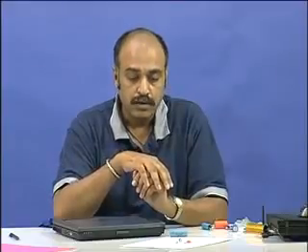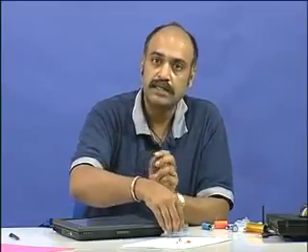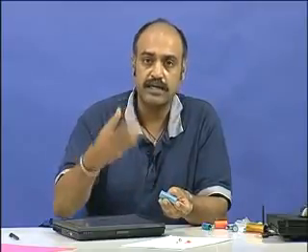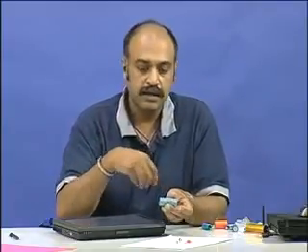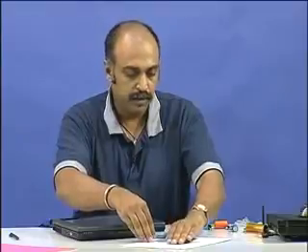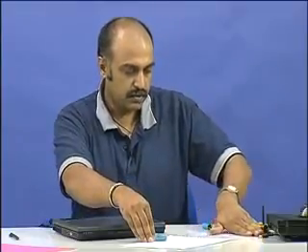Okay. So, a practical capacitor is not lossless, it has some loss in it due to these practical limitations. So, due to that the size also will vary. As the currents in the capacitor increase, the sizes will also go up because the ESR is going to dissipate that.